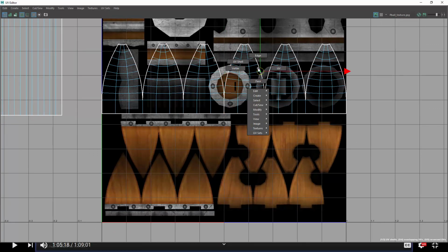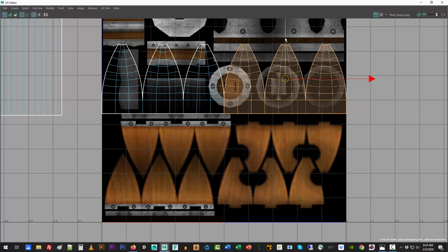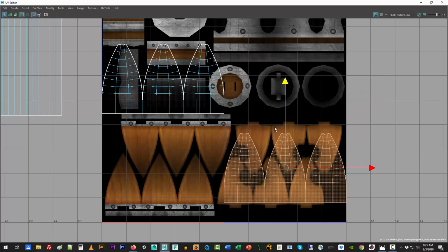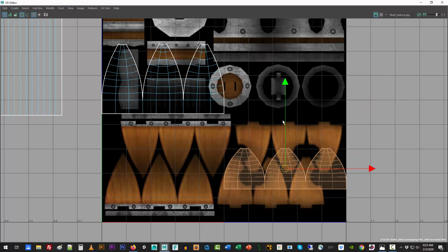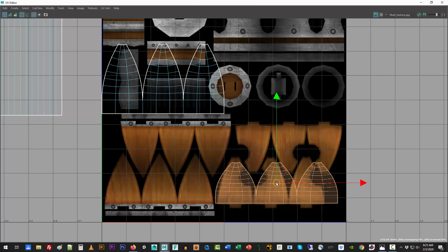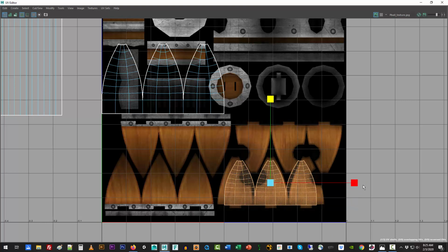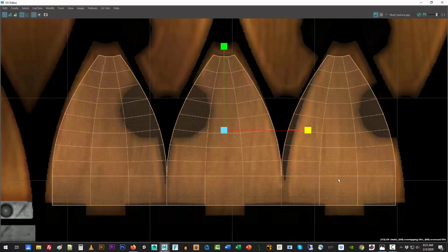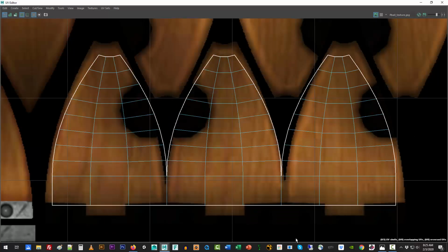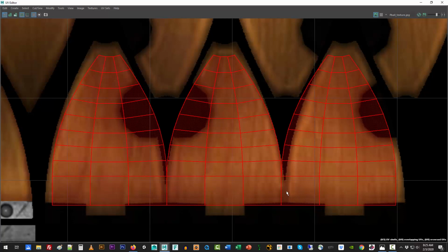Now, if you are so inclined, you can just drag your UVs one on top of the other, and then everything's inheriting the same texture. Yes, you can do that. What I'm trying to do here is match them separately. I know I could have grabbed them all uniformly, but I didn't want to. And I can get them pretty close, but look, there's an inconsistency. So what am I going to do here? I've got this kind of black line going.